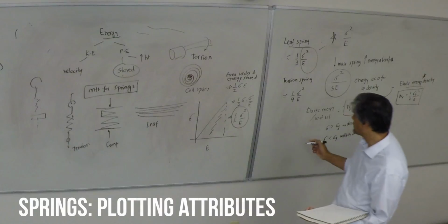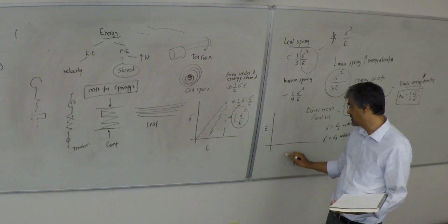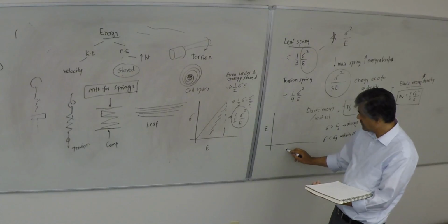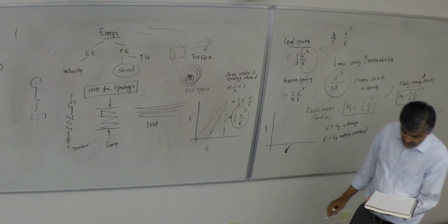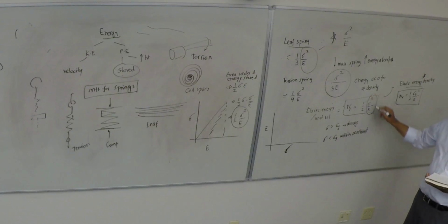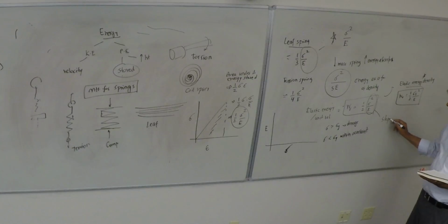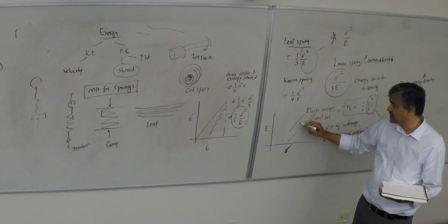So in this particular case, I would urge you to draw the modulus versus strength curve, like you did for fracture toughness versus strength. And again, because this is sigma f squared over E, you have to look for an index with a slope equal to 2, wherever that lies in the scheme of things.